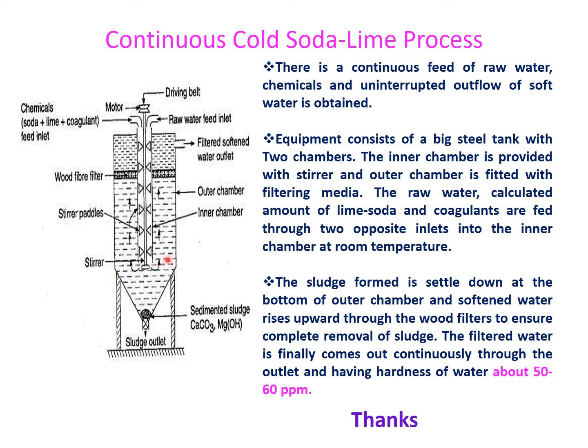The soda, lime, and coagulant will react with the impurities present in water, and they will precipitate these slurries like calcium carbonate, magnesium hydroxide, and other impurities, which will settle down in the tank, and by opening this valve we can remove them in the form of sludge easily.